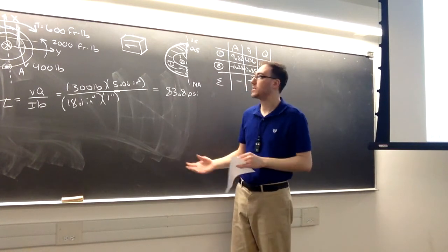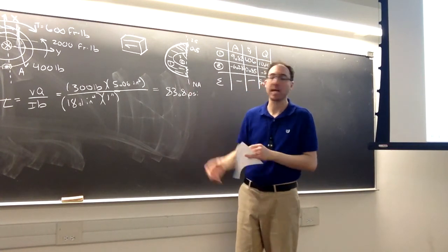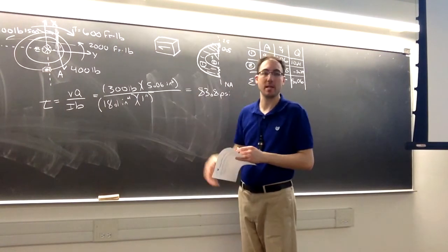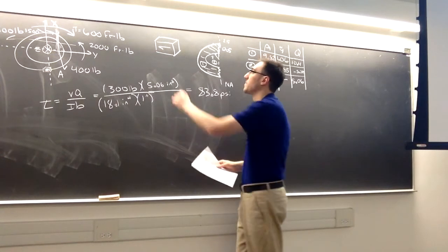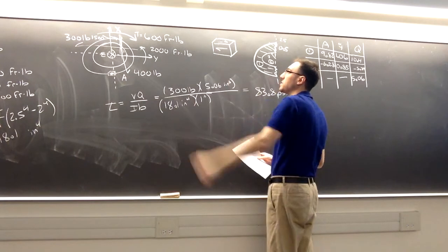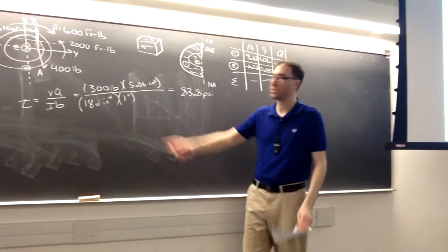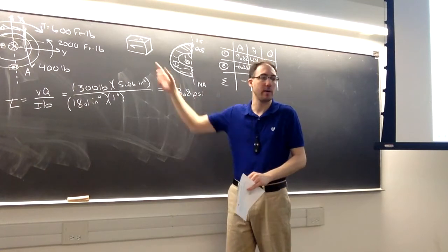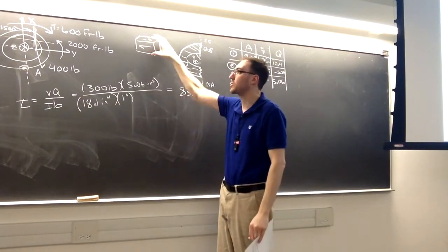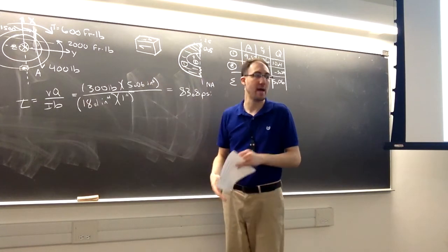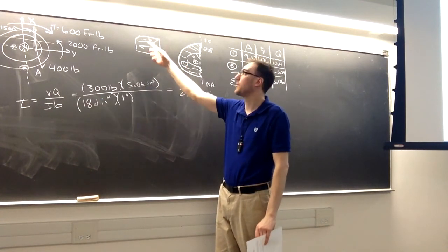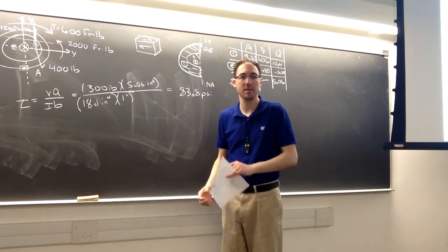Now, with shear stresses, everything has to be in static equilibrium. So if I have a stress going to the left, it's tough to see in this picture, but on the back face I have to have an equal and opposite force to counteract the stress going to the left. Not only does the whole thing have to be in equilibrium, every stress cube that we can make out of it also has to be in equilibrium. So this stress goes to the left, and to balance it out, there must be a stress on the back going to the right.